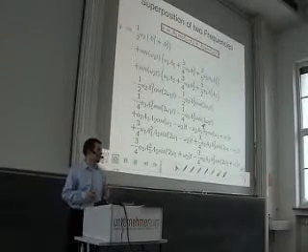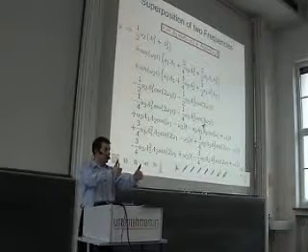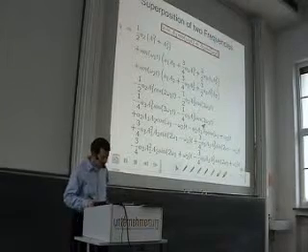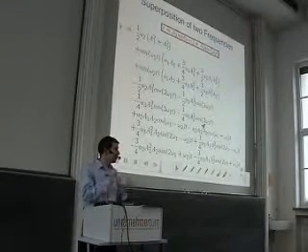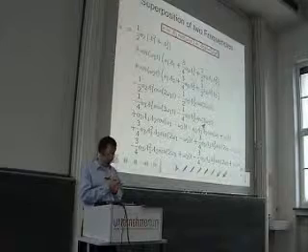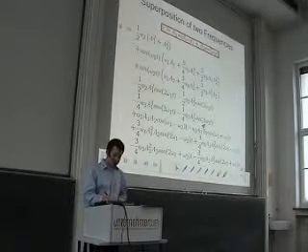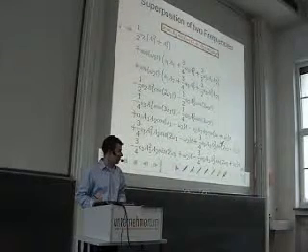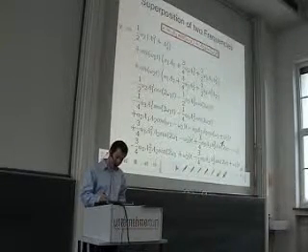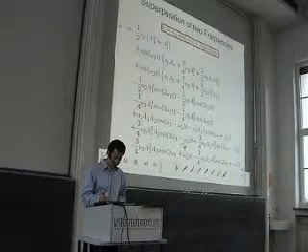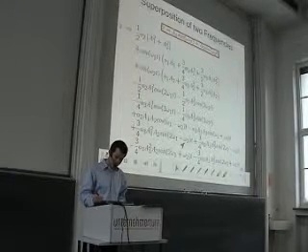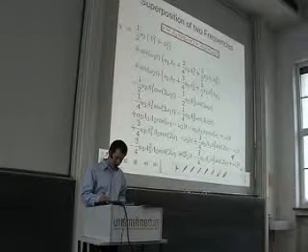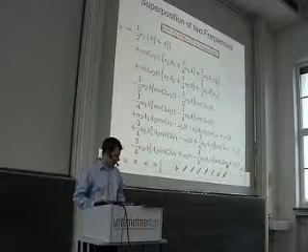So far, no surprise. We have the fundamentals. Each fundamental has its harmonics. And then what comes additionally is that these 2 frequencies are also mixed together. So we get the difference of the 2 frequencies, and we get the sum of the 2 frequencies. And also we get 2 times the first one minus the second one, and 2 times the second one minus the first one, and we get also a component like this.